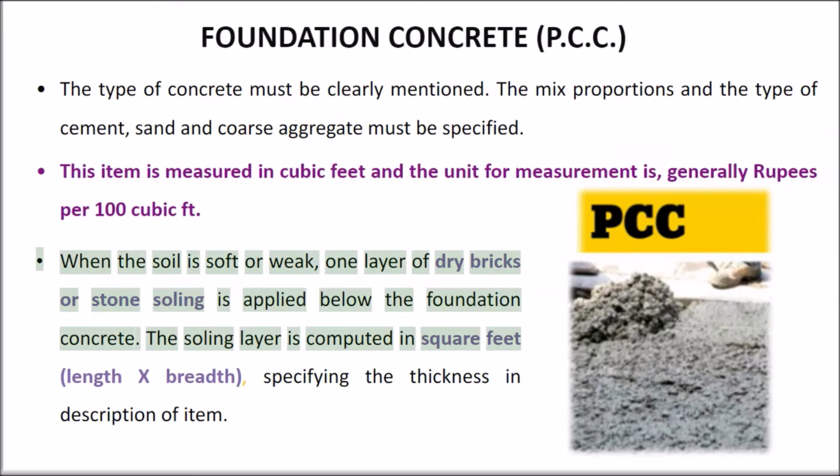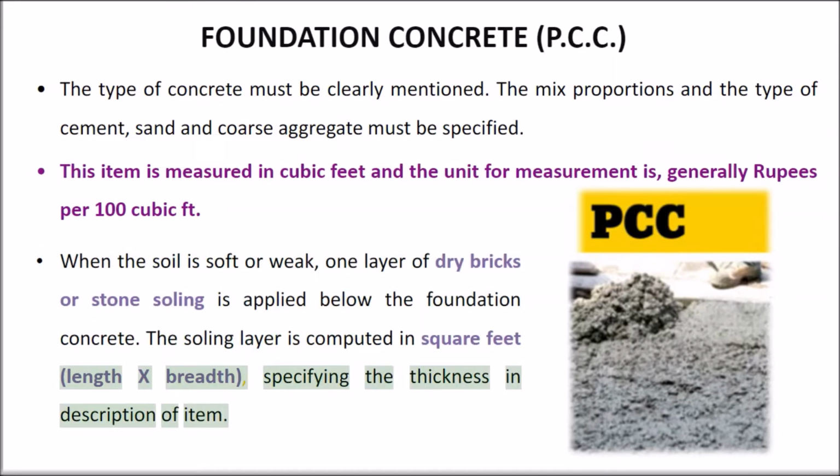When the soil is soft or weak, one layer of dry bricks or stone soling is applied below the foundation concrete. The soling layer is computed in square feet, length times breadth, specifying the thickness in the description of the item.